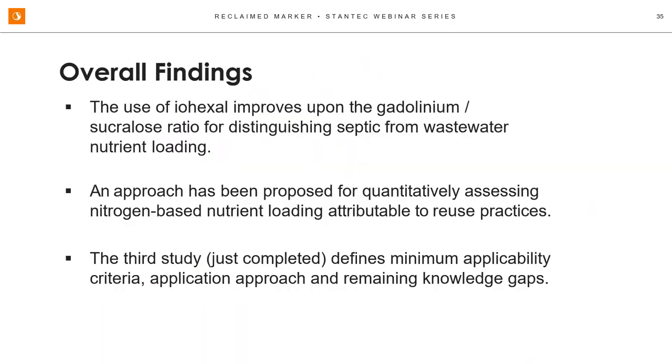So to wrap this up, our overall finding was that using iohexol was definitely an improvement upon trying to use the gadolinium-sucralose ratio for distinguishing septic from wastewater nutrient loading. So iohexol is a much better diagnostic contrast media to focus on than the gadolinium, at least for all of the study areas that we looked at.